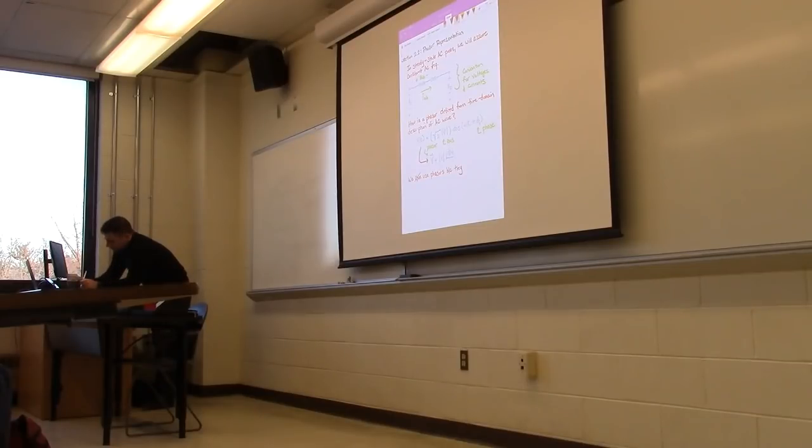So if we take a look at an equation from the book, equation 2.3, it essentially represents an RLC circuit in the time domain. So what does that look like, right? Let's just assume that they're all series elements, because I'm not going to draw the circuit. So we have R I of t, that's the voltage across the resistor, plus L di dt of I of t, plus 1 over C, the integral of I of t dt, equals,